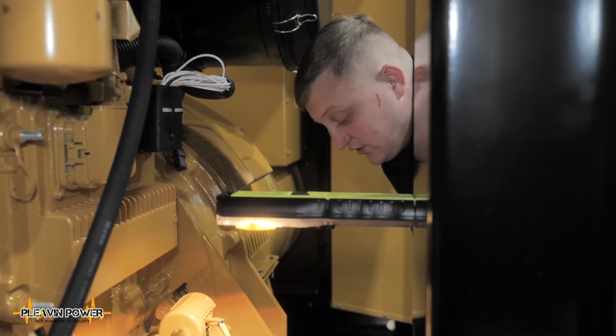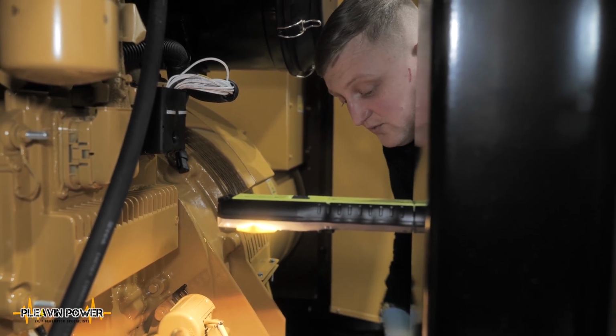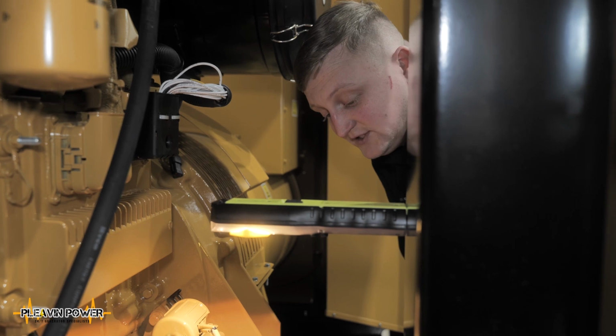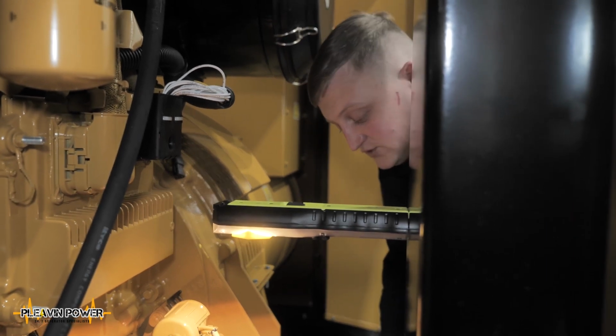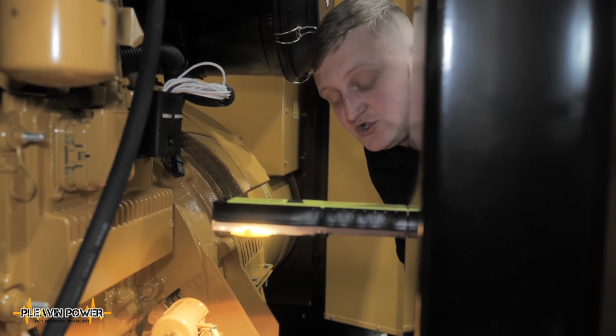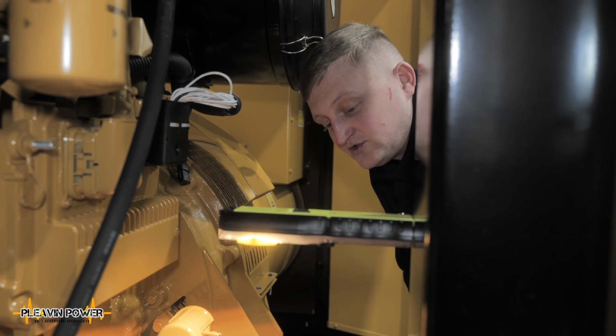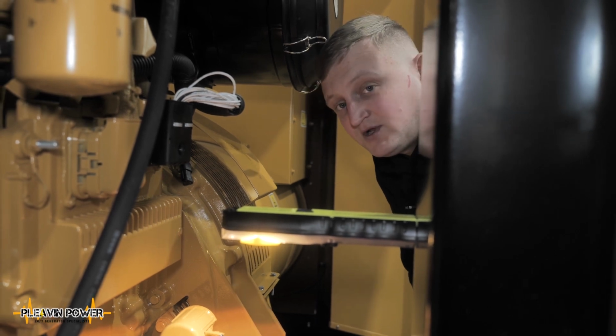The other thing to make sure of as well, not so much in this application but in a different application whereby the generator is installed in a building, is to ensure that the correct type, whether it be wet or lead acid or AGM battery, has the correct charger installed, so the batteries aren't suffering overcharging, undercharging or cell damage as a result of the incorrect charger being fitted to the application.